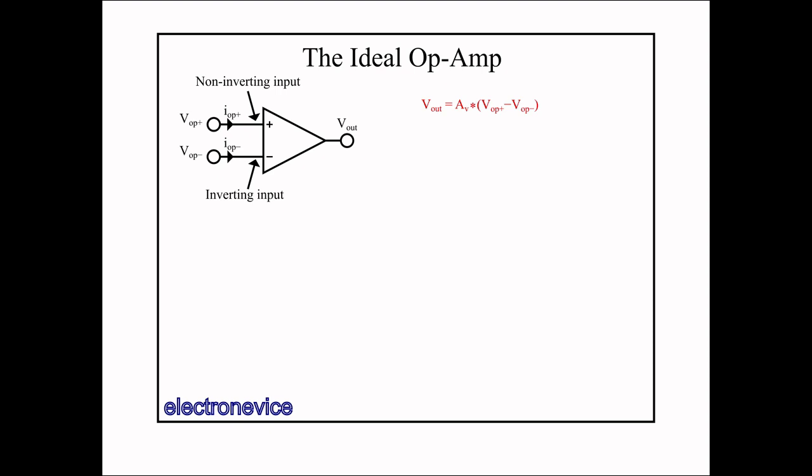However, this is not how op-amps were designed to work, and they will almost never behave well if you try to do this, because AV is designed to be very large, usually at least 100,000 volts per volt, with some op-amps going up to 1 million volts per volt. This makes it difficult to use them this way to amplify most signals, as most signals don't need that much gain. They perhaps need a factor of 1 to 1,000 for most applications.